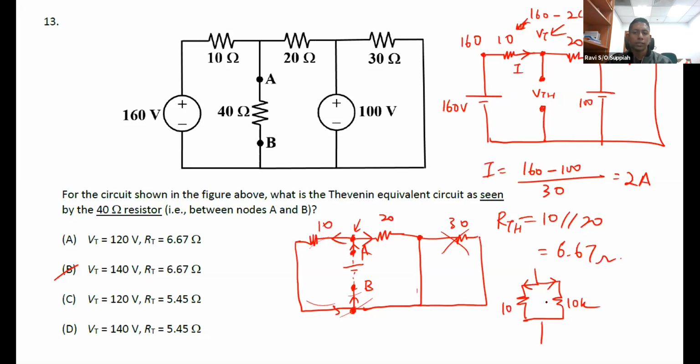Okay, so the same thing applies here. So imagine that with this same concept, I slowly keep decreasing the smaller resistance and I slowly keep increasing the higher resistance. That means over time, the current through this 10 ohm branch, if it slowly becomes 20, 30, 40, and this one becomes 30K, 40K, 50K, then what happens? The current through this branch will become smaller and smaller and smaller.